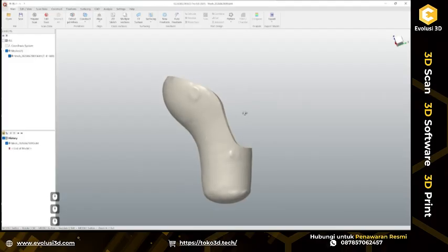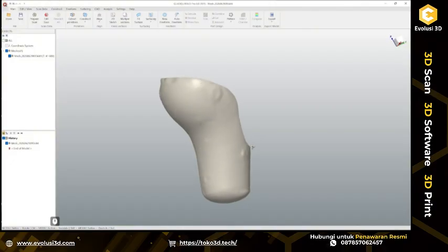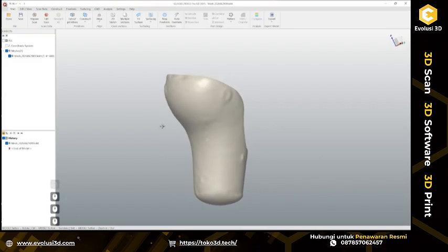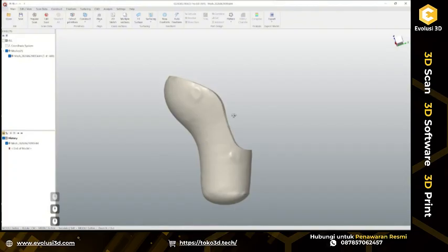Right now I'm looking at this part and I can see several approaches. First, we can try to fit some primitives, then loft all that together. Probably this might work, but there is never a guarantee that it will work. Same, we can try to create a 3D curves network and then create a fill surface based on that. Also, we can always use automatic freeform in such cases, but we have to keep in mind that we need to keep it as low resolution as possible.